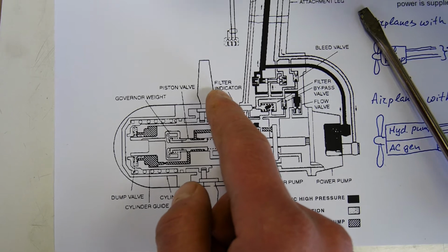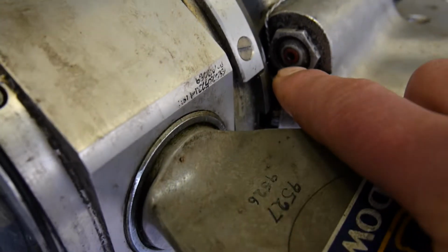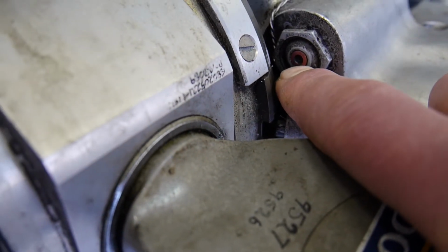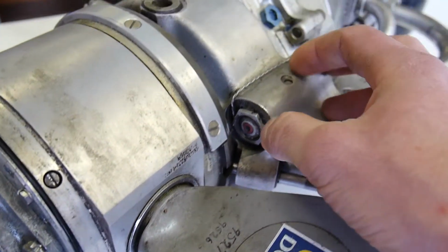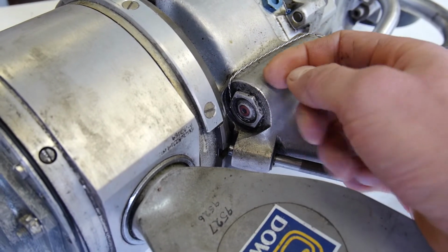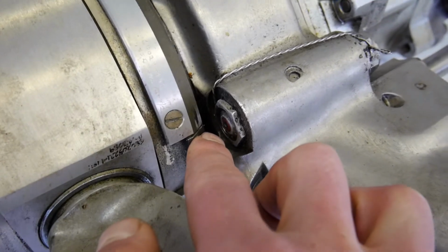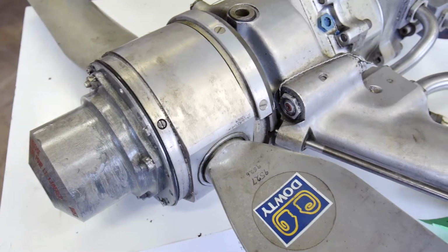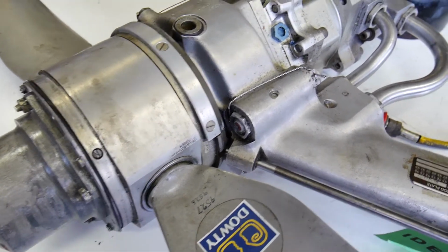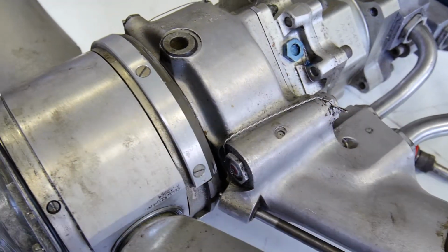of the oil filter bypass indicator. This bypass indicator is here, so this red tip. Yeah. Now it is in a good position. Yeah, everything is good. When the filter becomes contaminated and bypass opens, this rod is released, and it appears here, yeah, for a few millimeters. And further, during visual inspection, we can see that, oh, we see this rod, so we have to replace this filter. Yeah.